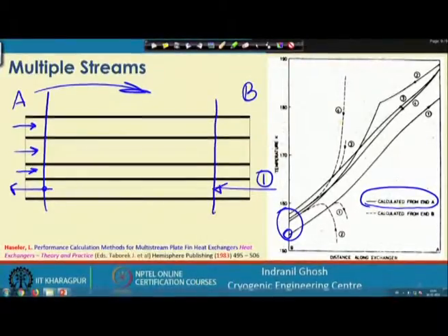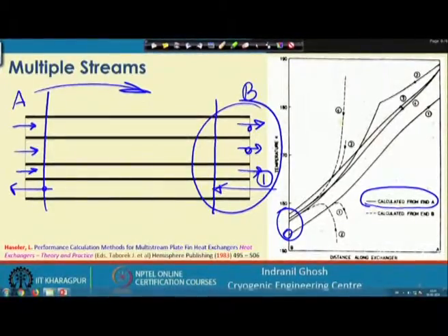End B means, what she has to do is that they are coming like this. If we have to simulate from this end, one has to assume the fluid temperatures at these 3 points. So, even if someone is very close to the actual exit temperatures, and tries to start the simulation from end B, very soon the solution will diverge.